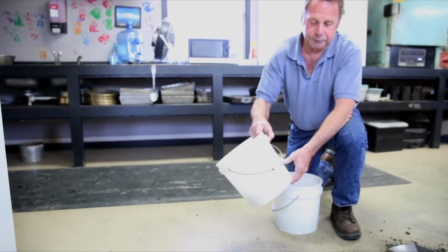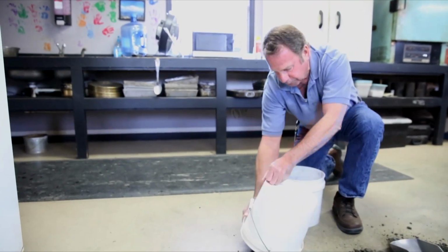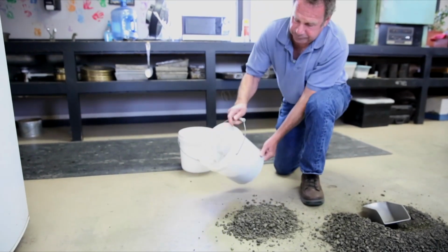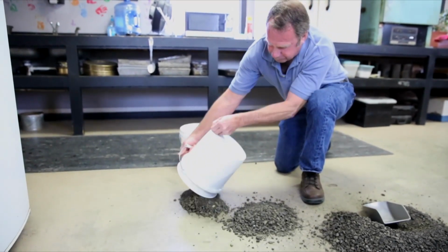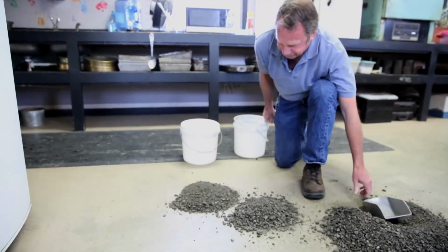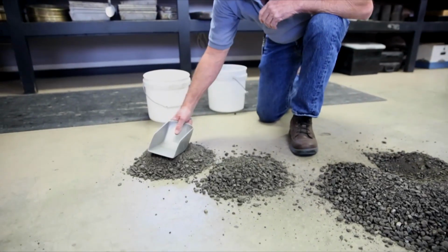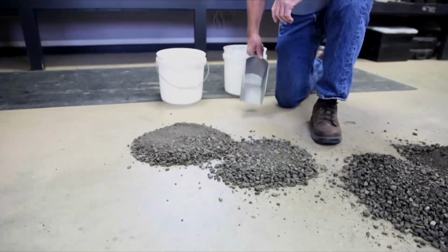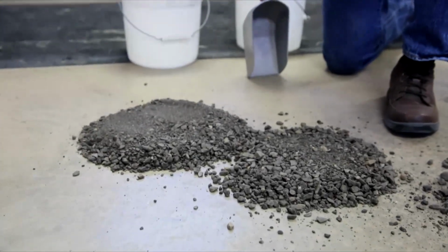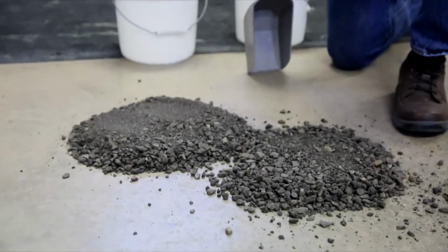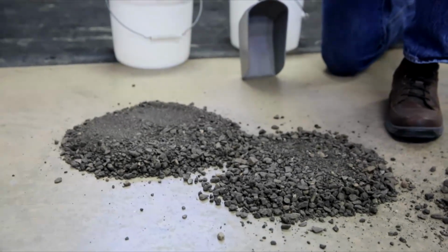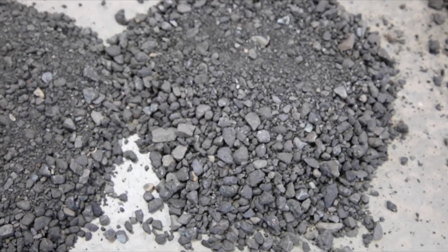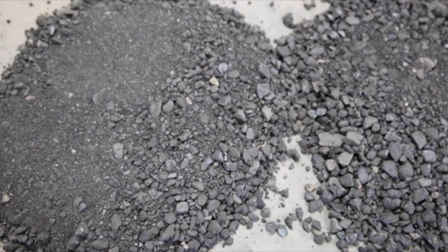Okay, here is the first material that I put into my hopper. And here is the second 3 scoops that we put in the hopper. And you can see, and you will see on the next set of slides, the difference in the gradation and the binder content, but you can physically see there is a dramatic difference between the first 3 scoops and the second 3 scoops.